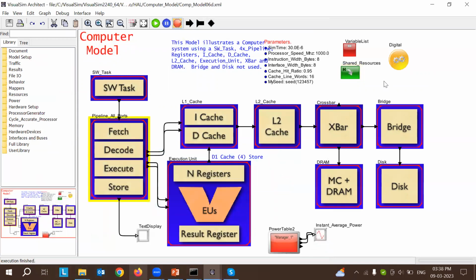This kind of modeling requires complete details of the possible flows, which can be reflected using the cycle-accurate design. The system resource block delays each operation for a specific time as per the specification. This approach doesn't care about the internal logic, but it achieves faster design and evaluation. In this model, the traffic is configured to send each task at a 30 microsecond delay, and each task contains 4,000 instructions. For the entire traffic, 90% of them are ALU instructions, and 10% of them are load store instructions.